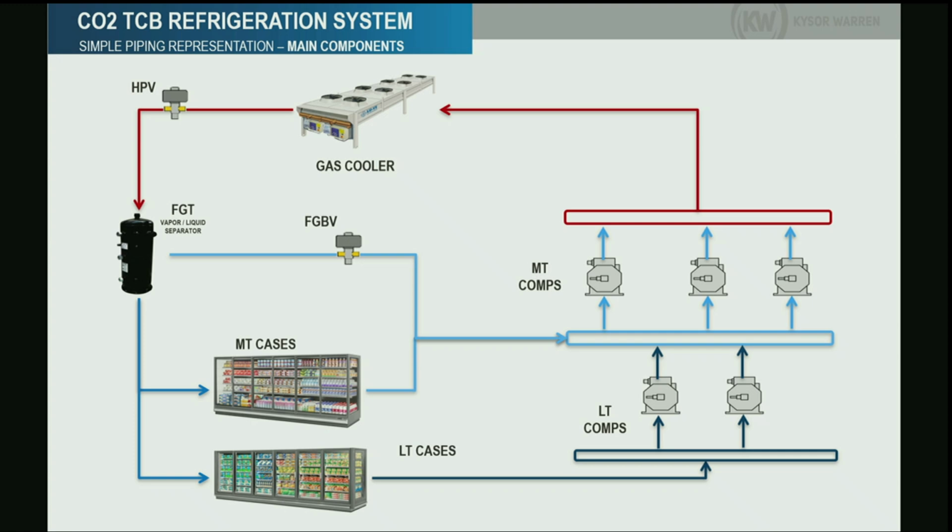Because of this, when people are doing a startup of the system or a startup in the store, we need to always run the medium temperature compressors first and then the low temperature compressors. That is very important when you are doing a startup.